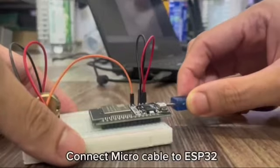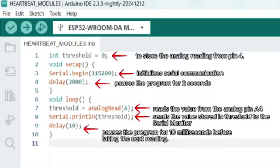And lastly, for module 1.1 is coding explanation. First line is to start analog reading from pin 4. Third line initialize serial communication. Fourth line process the program for 2 seconds. Line 7 reads the value from the analog pin A4. Line 8 send the value stored in the threshold to the serial monitor. And last line pauses the program for 10 milliseconds before taking the next reading.